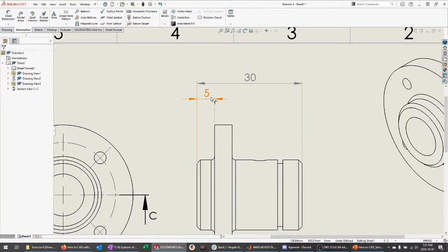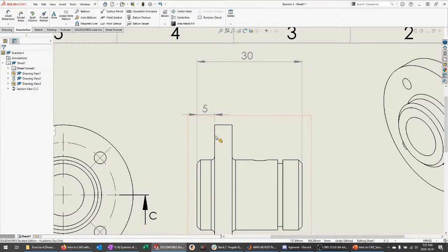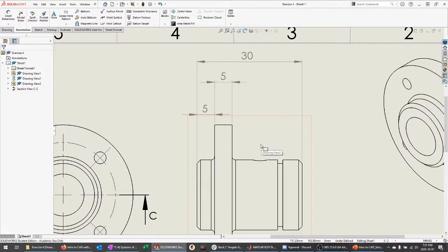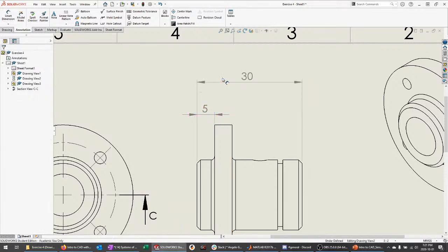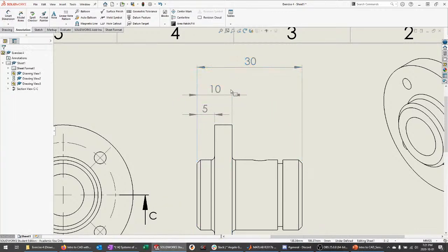Adding a few dimensions. If it's something you're CNCing, then if you have a drawing handy, that'll generally be so you can measure the part after it's made, and verify that the dimensions are what you like. So in that case, you'll tend to want to dimension things that are easy to measure. Like the thickness of this flange is easy to measure with a pair of calipers. So you could do a 5, as opposed to, you could also dimension it like that.